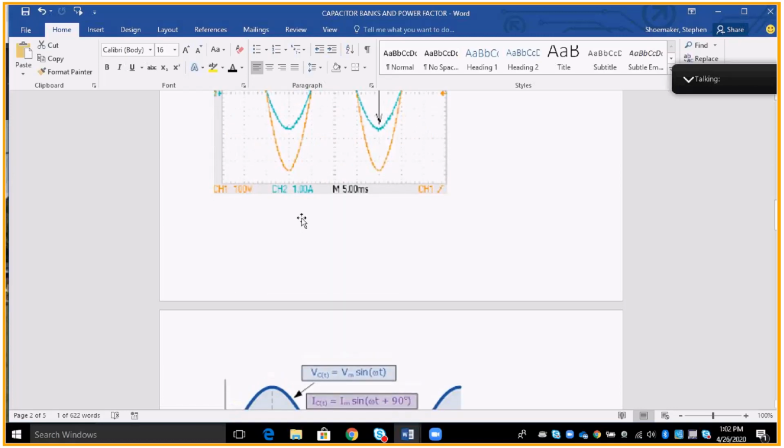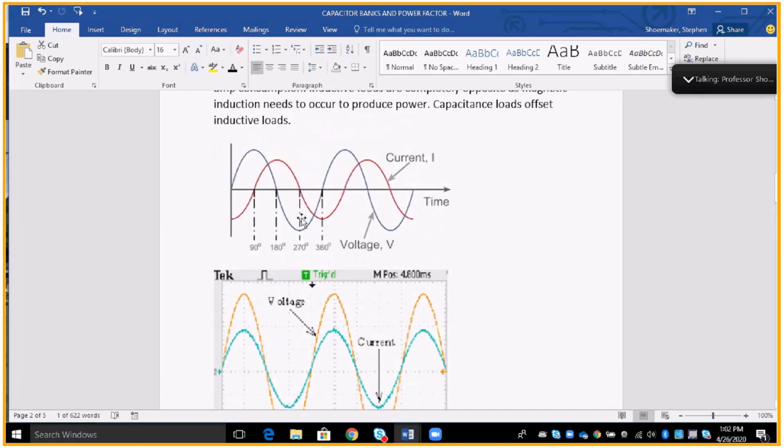On the other hand, when I have to induce voltage to a component such as a motor, there's a timing issue because I have to create and receive a magnetic field. The motor at all times is going to be wanting power before my voltage can get to it, because it's having to go through the magnetic field process. The blue line is voltage. My voltage is peaking here, but my motor is asking for the amperage, trying to turn its hardest, here. So this is an inductive load.